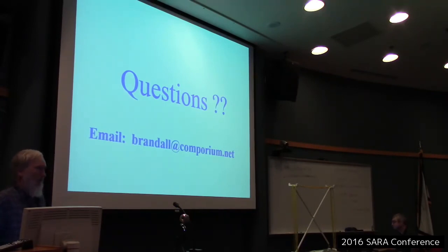So all of a sudden you have all these cables. The connector on the other end was pretty expensive, so they cut it off. So I have all these cables right here, which have an MCX connector on one end, the same as used on those little USB dongle units. The other end is just a plain piece of coax. It's put your own connector on it.